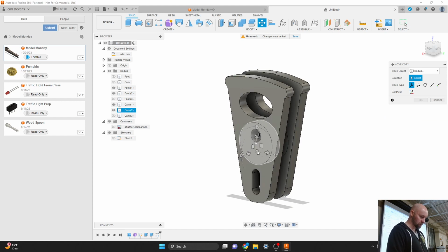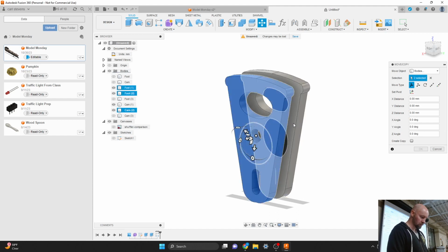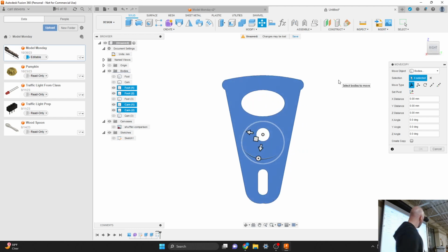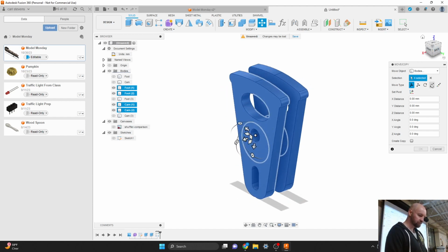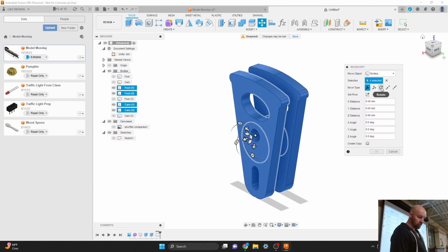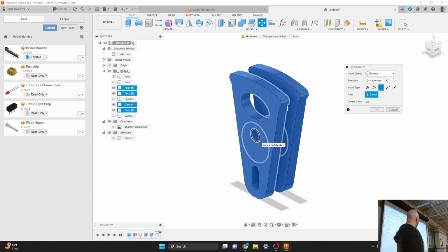An alternating action. So you almost need an axis line through the small hole for alignment. Yeah, like this is our rotational point here. So now, if we've got them all selected, we can choose the rotate option here in our Move tool, and we can specify an axis that we're rotating these around, which I think is going to be this little one.